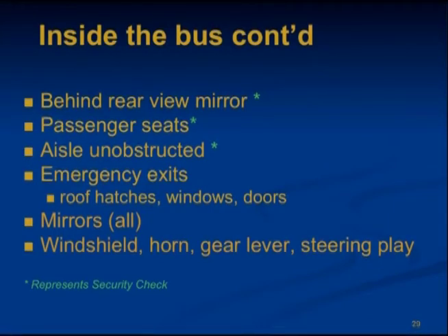Make sure emergency exit doors, windows, and hatches are all able to open and close freely. Doors should latch properly from inside and outside the bus. Make sure that warning alarms work, that handles are not broken, seals are tight, and make sure that you know how to operate all emergency exits and instruct your passengers how to operate for evacuation. The roof hatches should be in a latched position. Look for anything out of the ordinary.